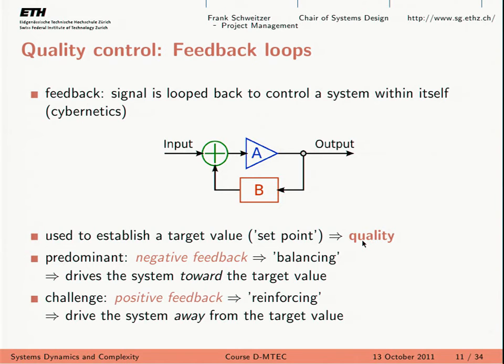But also, it doesn't have to be as abstract as this. If you take a microphone and you go next to a loudspeaker, even if you don't talk, you would get this squeaking noise, right? Because the random noise, which is not perceived by you, gets amplified by the microphone, comes out amplified from the speaker, gets picked up by the microphone again, gets amplified even more, gets picked up again, and then in a couple of milliseconds you have this explosion. So these are the positive feedback loops.